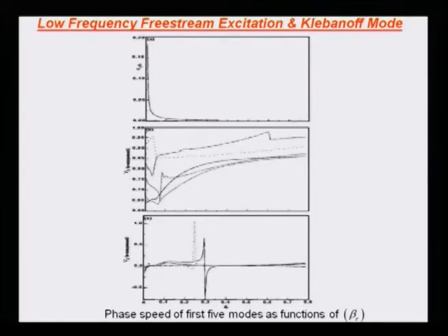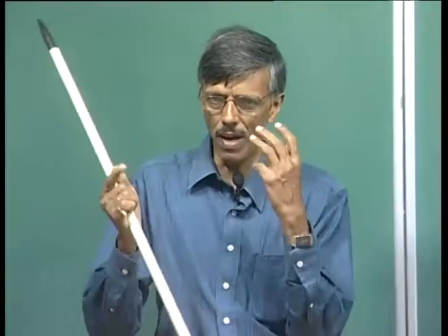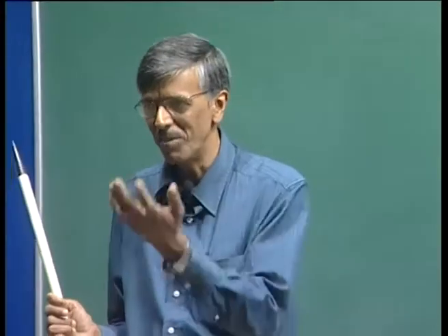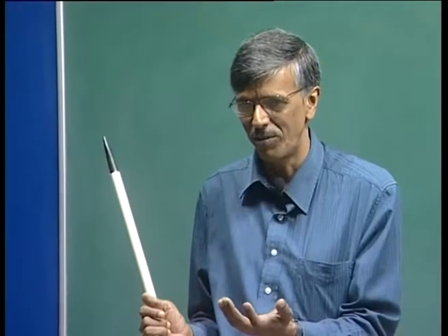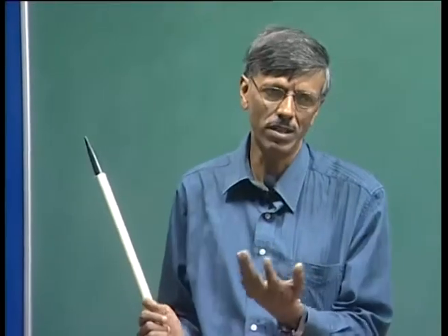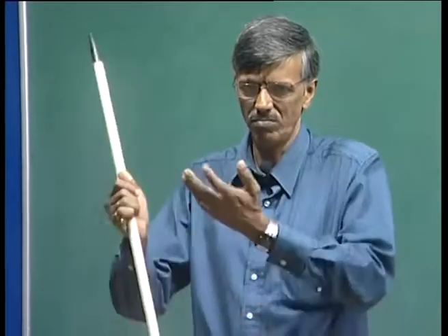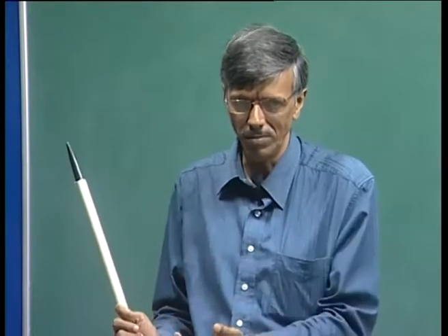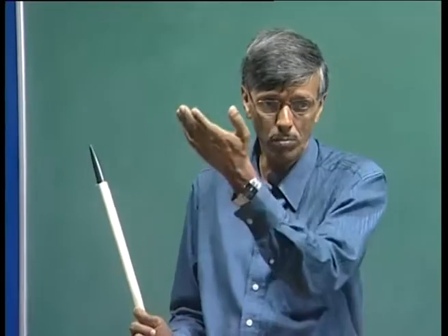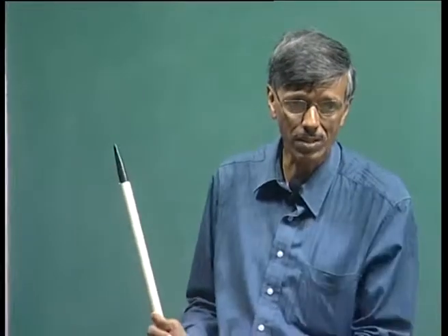So it would appear as if, if I look at that tunnel, the phase is not moving. It would appear as if it is stationary. That is what was giving us the impression of a breathing mode. We are having a 3-dimensional flow field, but C phase is virtually 0. So we are seeing as if it is staying in the same place, but with time, because it is changing with omega naught, we have fixed it omega naught. So the whole boundary layer is heaving with that omega naught.